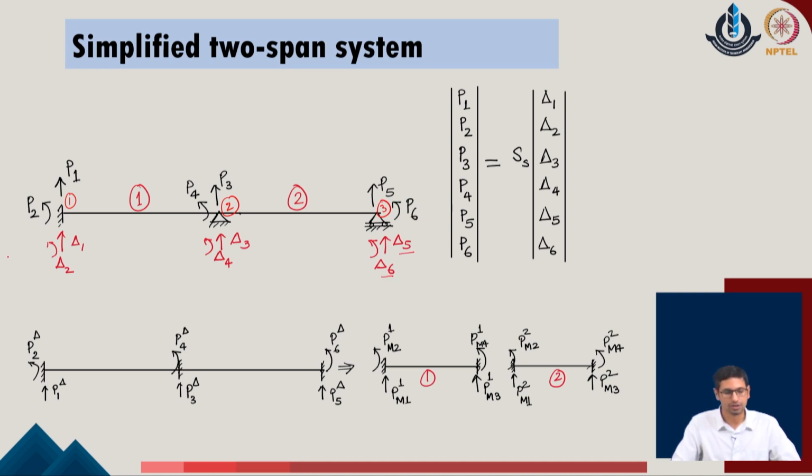Now, this is the condition which is available with the global system. Accordingly, we will also be converting the equivalent joint loads in the given problem. Say these values come out as P1 to P6. So, we will be writing the equilibrium conditions corresponding to these 6 force values, and the right hand side will be identified in terms of 6 unknown displacement parameters as well as the displacement parameters corresponding to the restraint supports of the given problem, and they will all be connected through a stiffness matrix of the overall system.